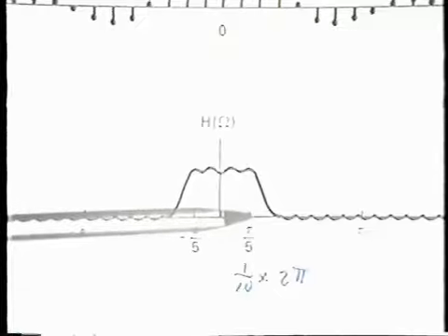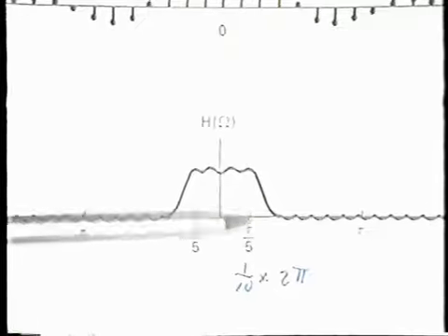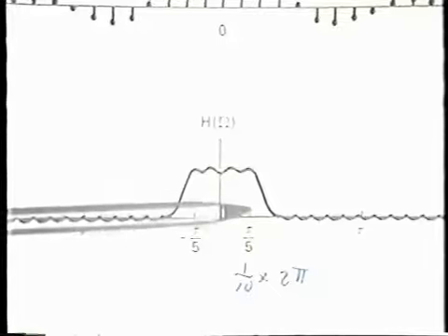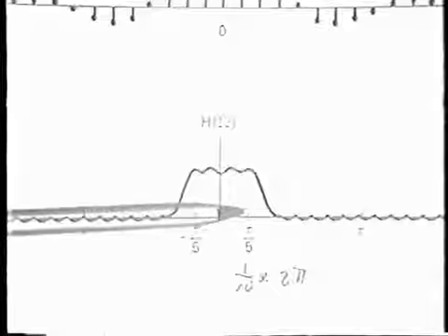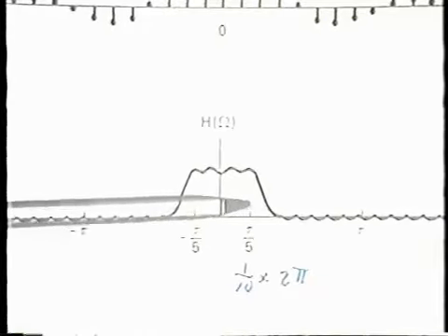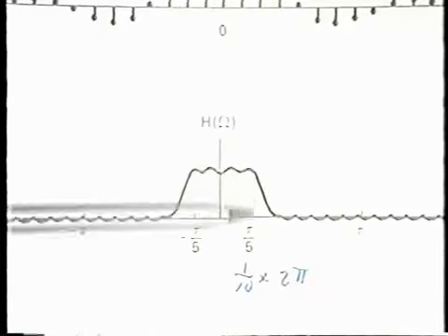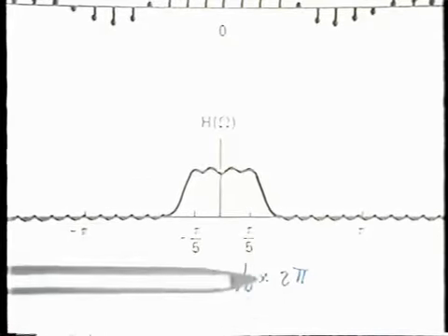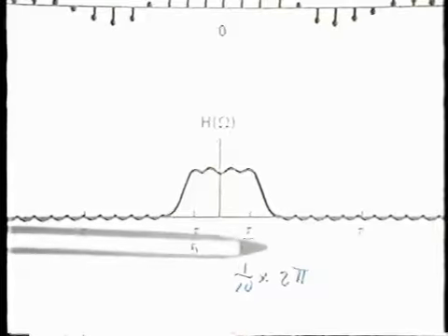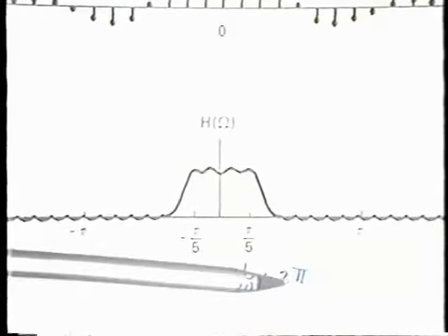And as I'll stress again shortly, remember that in the frequency normalization or unnormalization, 2 pi represents, in effect, the sampling frequency. And so the consequence of that is that the cutoff frequency really is going to be associated with a tenth of the sampling frequency. But for now, keep in mind that it's just simply a tenth of 2 pi.